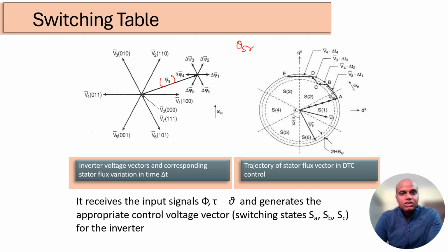So let's say this is the stator flux vector, which is shown over here, currently the present stator vector. If I choose the vector, let's say V2, which is 110, for a shorter period of time, let's say del t, then the actual vector now becomes a resultant of this. So the angle is being increased. My stator vector gets moved ahead by this angle, which is more than the previous angle. So by choosing the right vector, I can increase the torque.